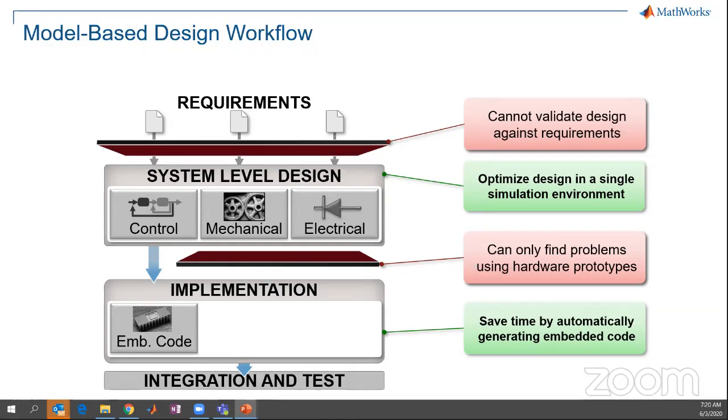In the hardware testing stage, a lot of times we have to tune our controller parameters to make sure our hardware performs correctly based on the requirement. So all we do is change our code, but not change our simulation. So by the end of the project, the modified C code and the simulation are not always consistent.